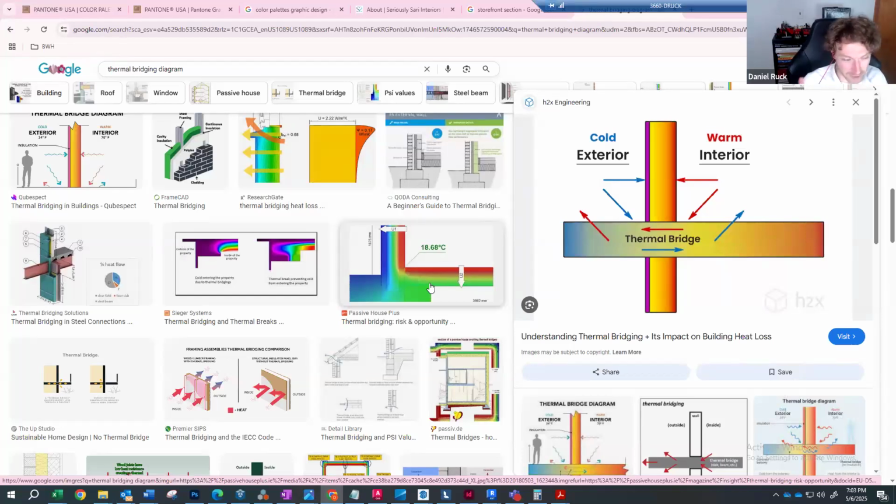It gives you these colors, like army night vision, where you're reading heat temperatures to get vision. It shows you where there's thermal bridging within your envelope. If things aren't sealed properly or insulated properly, you're going to get thermal bridging, which is the transfer of temperature either inside your building or outside of your building.